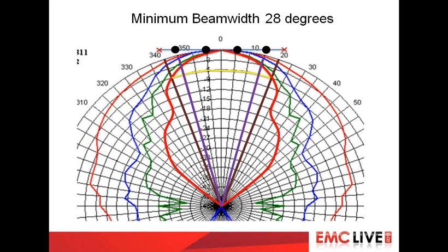So there's a visualization of the calibration plane and how it's been illuminated and the particular limits and don't cares, etc. Also the absolute minimum beam width we want to see on there. If this antenna has a beam width of less than 28 degrees, then you're getting very, very tight, and it's going to be unachievable. Your goal is unachievable. You're pretty much wasting your time.